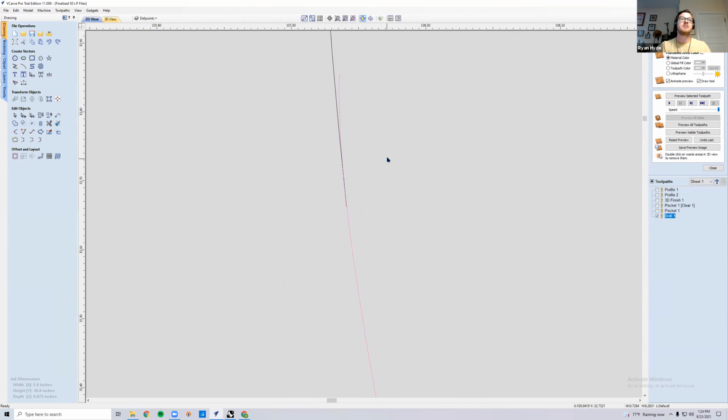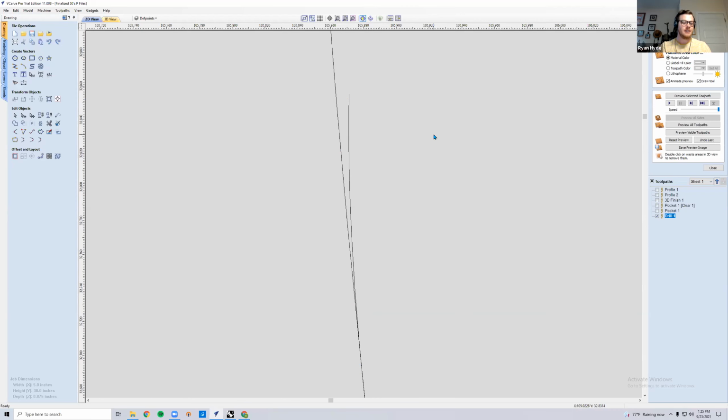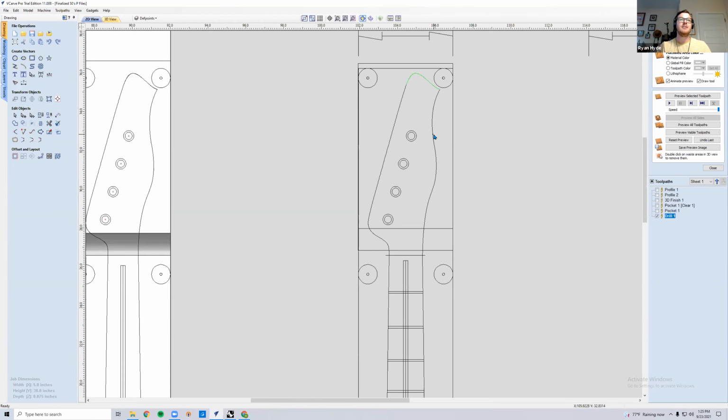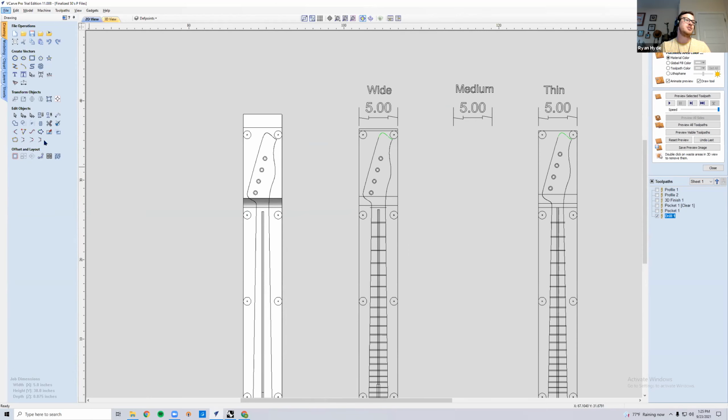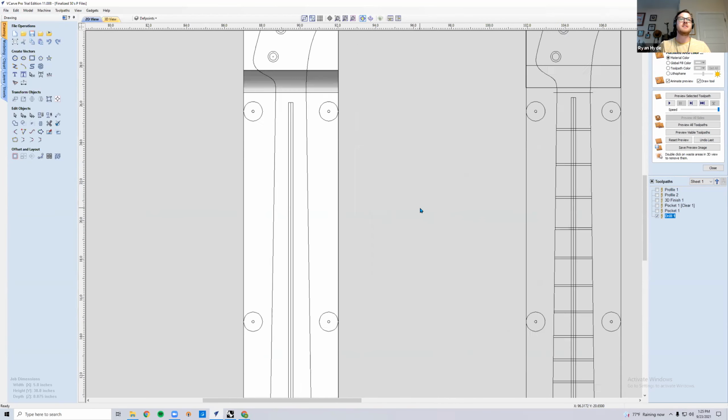There's a special hiccup where this line right here, this small bit of overlapping line work that I forgot to clean up in my original CAD program, was a big no. This program was like, no. So I just did a little bit of work to edit and clean this. I just used this little scissor guy and snipped it out, basically, and then used a couple commands, like the join command over here, to squeeze all these things together.